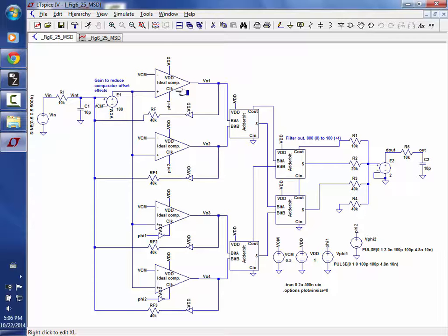You can have it reset on the next clock edge, or if you want a wider pulse, it could be 2 clock pulses down. Okay, so the key point is, if I go with this topology, this guy makes a decision, and then he says, okay, I go high. Well, it feeds back that high for the entire 10 nanosecond clock pulse. By the time it comes back around, it's still putting in that old information.